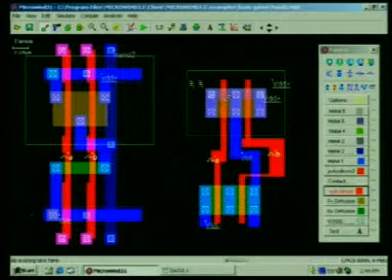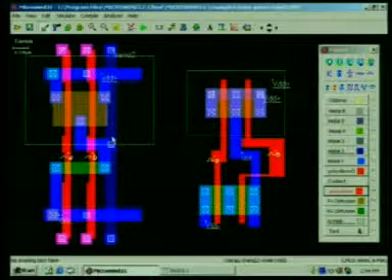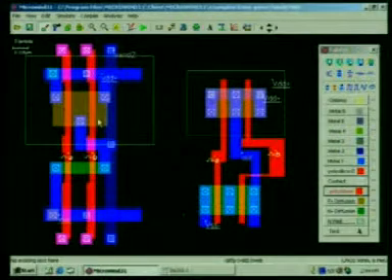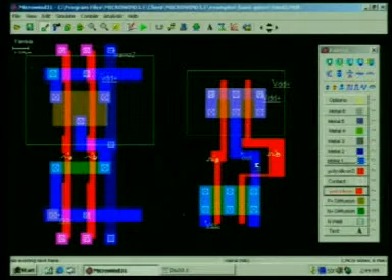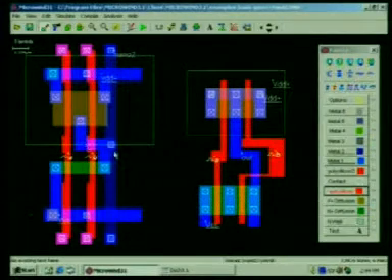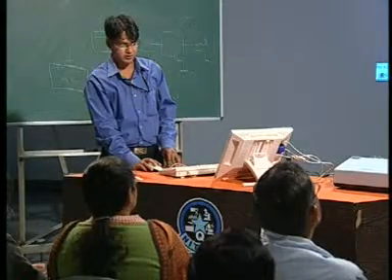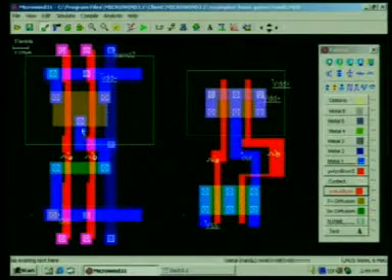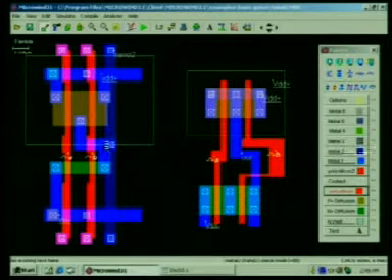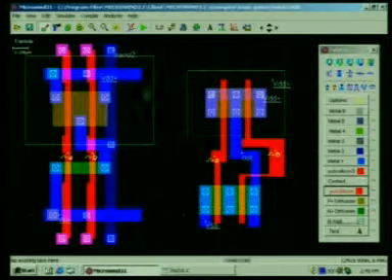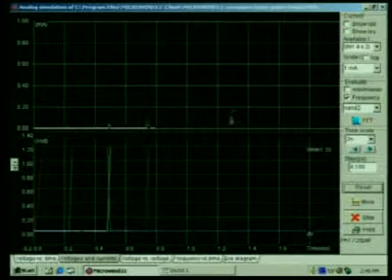See, this one is unoptimized actually, and this is the optimized one without error, and I have used metal layers here. This approach is not actually good. I have to put more and more contacts, and I can use different kinds of metal layers. So, see this, here they have connected here, and then here they have put another connection for metal 2 layers, and now I will delete this one, simulate this one.